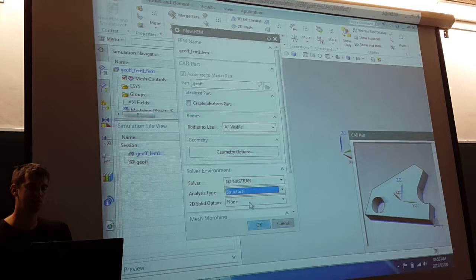Okay. Next what I'm going to do is create a 3D mesh. I'm going to mesh this body. So I click on 3D tetrahedral mesh up here. It's in the collection of mesh options. First things first, I need to select the body that I want to apply the mesh to, and that body is Jeff. So we click on him.